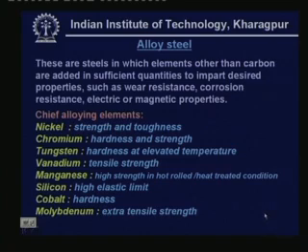So, tungsten steels are supposed to be one of the very hard steels, and in certain cases, if you are using small bearings of journal type, then you can sometimes use tungsten bearings, which, because of their hardness, won't wear out that rapidly. Vanadium simply increases the tensile strength. Manganese gives high strength in hot rolled and heat treated conditions.